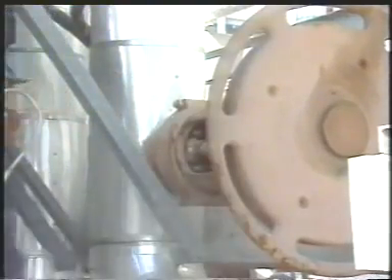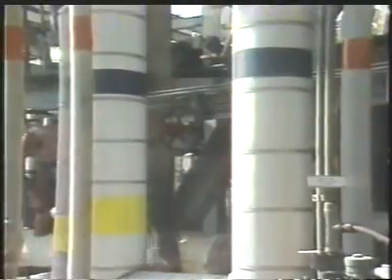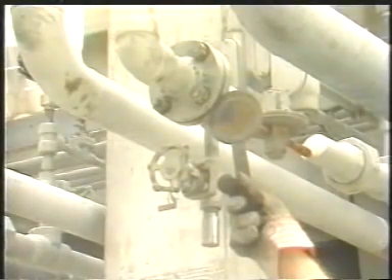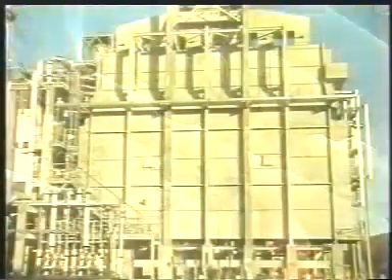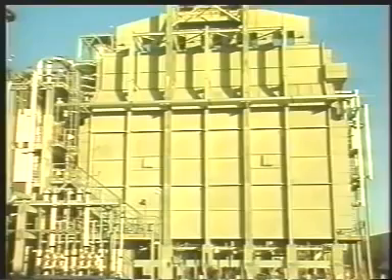And when the furnace is cool enough, stop the process flow and block the process systems. Next, you purge the process tubes with steam. Each individual pass must be purged. After purging, make sure all burners are isolated and that all main and pilot fuel headers are blinded. This completes the normal furnace shutdown operation.